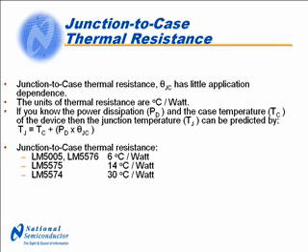For the new simple switcher devices, they're available in 3 different packages, which I'll explain later. But for the LM5005 and the LM5576, the junction-to-case thermal resistance is measured at 6 degrees C per watt. For the LM5575, it's 14 degrees C per watt, and for the LM5574, which does not have an exposed pad underneath, it rises to 30 degrees C per watt.